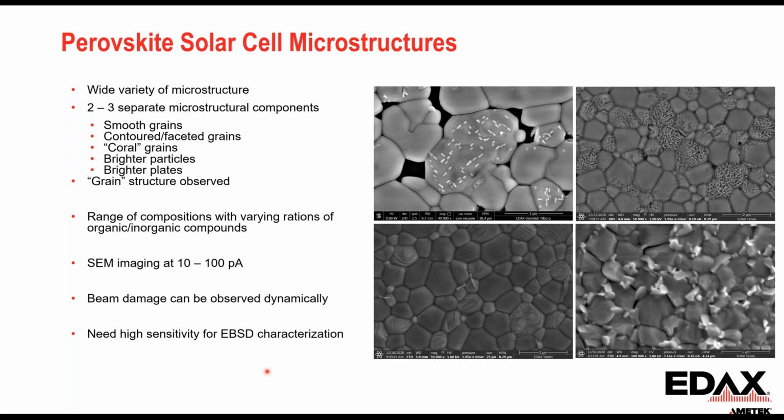And the important thing is, even to look at these with SEM images, you need very gentle beam dose conditions. You can actually watch the beam damage occur. So for EBSD characterization, we need very high sensitivity, and that need increases as the beam sensitivity of a sample increases as well.